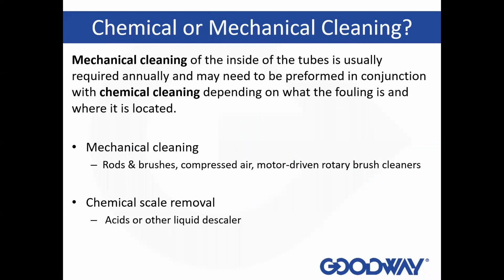It's a pretty tricky job to treat water that's in a boiler. That constant temperature change from one extreme to the other really tends to pull the minerals out of the water and coat the outside of the tubes. And not everybody gets that treatment quite right to keep the outside of the tubes good too. A lot of times that gets neglected, and you might have a nice clean boiler tube, but on the outside it's still scaled up and still hurting your efficiency.